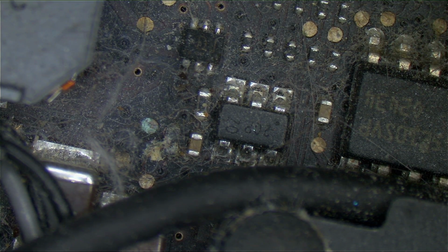The fourth thing that could be bad is this capacitor. If this capacitor is bad, again, this 301 kilo ohm resistor is sitting between here and here, but if this capacitor dies and it becomes a wire, if this link breaks and it just shorts, then this resistor is just erased from the equation. So one way to figure out what it is.